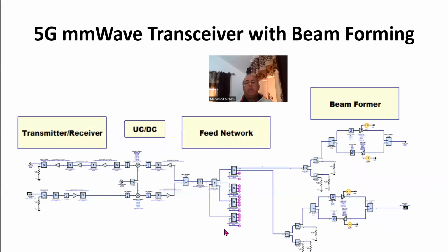And then I've got a passive network of 1/16 using a 4-way splitter, off-the-shelf thin film power divider. And then I have my beamformer implemented as this. Right now, it's not popular. What I designed, I left these open because these dividers have high isolation, so I don't even need to worry about terminating these with 50 ohm. You could terminate them with 50 ohm if you want to, but I didn't. So I just implemented these 2 branches emulating a transmit and receive path.